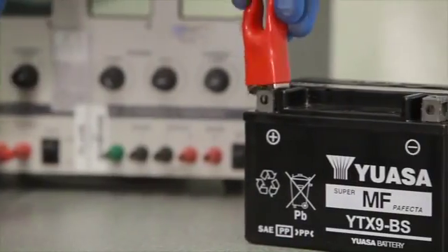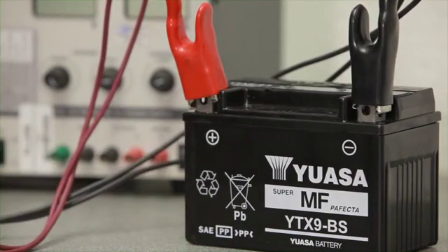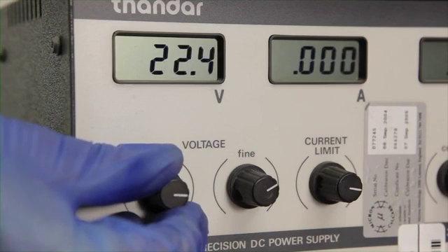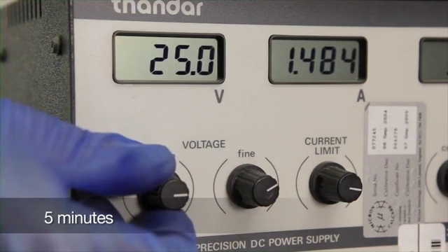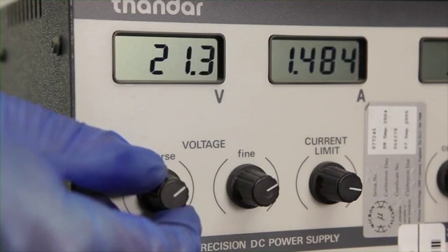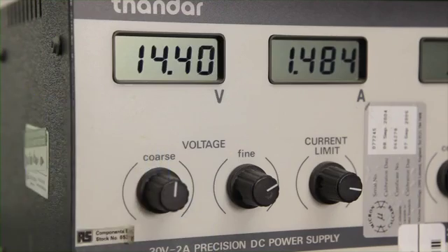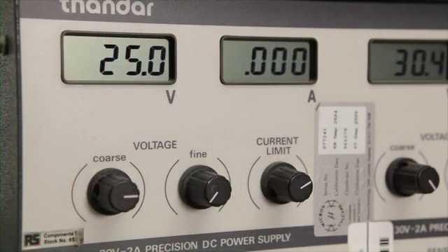If voltage drops below 11.5 volts during an unloaded test, specifically on a sealed battery, and the battery will not accept a charge at a normal rate, increase the charging voltage to a maximum of 25 volts for 5 minutes. If after 5 minutes the amp meter on the charger shows that the battery is drawing current, decrease the voltage to standard level and charge the battery for approximately 20 hours. If the battery fails to draw current after 5 minutes at the high rate of charge, the battery needs to be replaced. For more information on battery charging, consult the Yuasa technical manual.